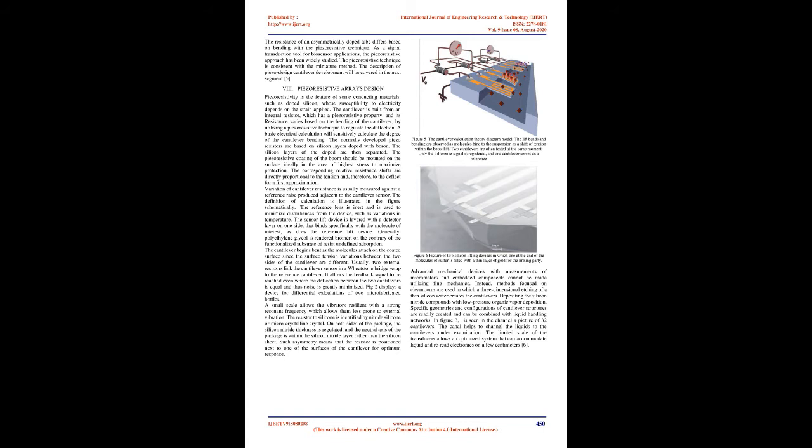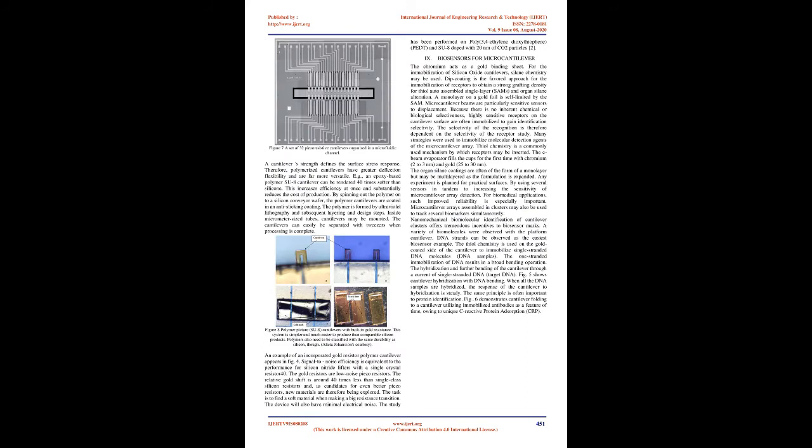The normally developed piezoresistors are based on silicon layers doped with boron. The doped silicon layers are then separated. The piezoresistive coating of the cantilever should be mounted on the surface, ideally in the area of highest stress, to maximize sensitivity. The corresponding relative resistance shifts are directly proportional to the tension and, therefore, to the deflection for a first approximation. Variation of cantilever resistance is usually measured against a reference cantilever produced adjacent to the sensor cantilever. The measurement is illustrated schematically in the figure.